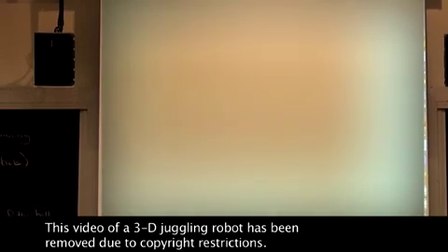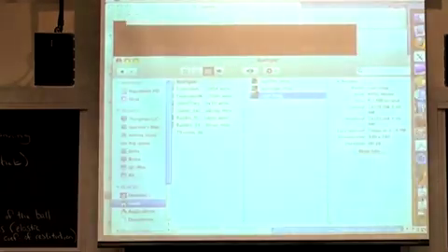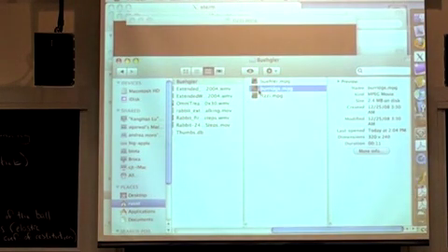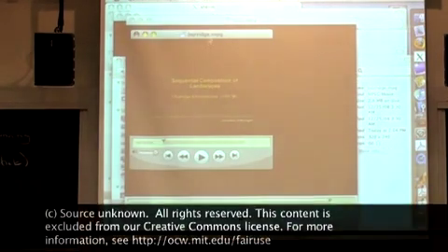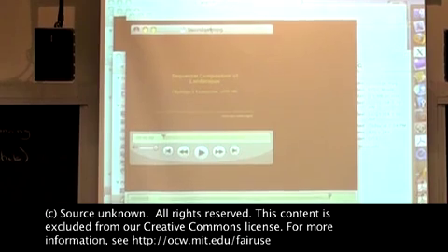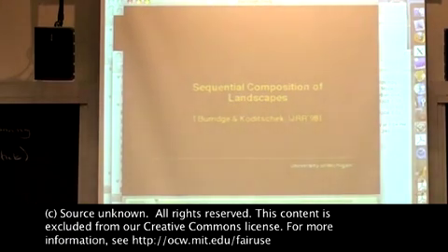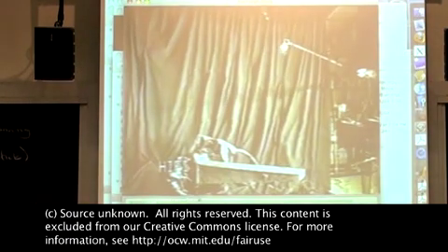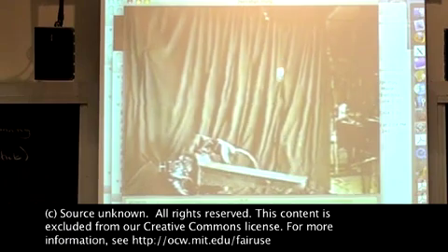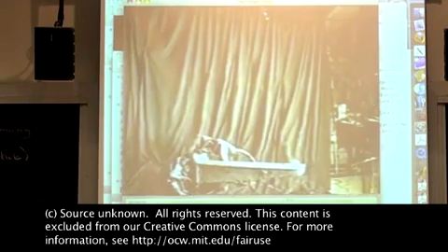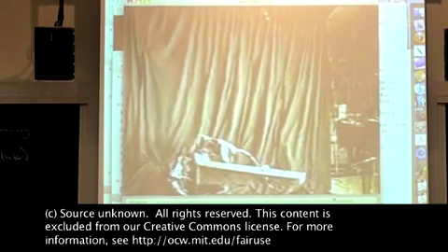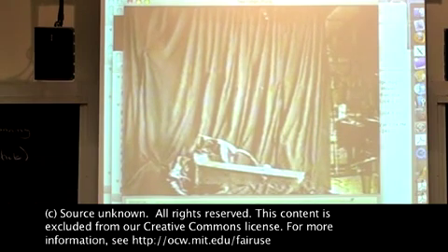And then they got so good that they started doing other maneuvers like catching and palming and things like this. It's actually turned out to be pretty much the same control derivation. They just set the desired energy to zero, and suddenly they have a catching controller. And then this is palming when they're doing their thing, okay? And then they can get it back up to catching with the same sort of energy shaping.